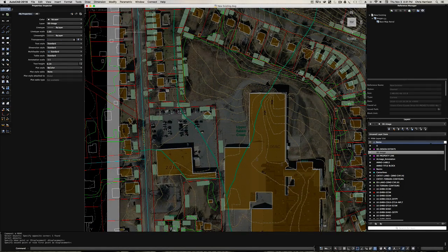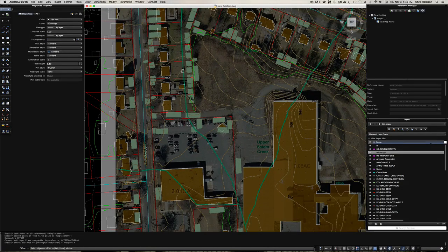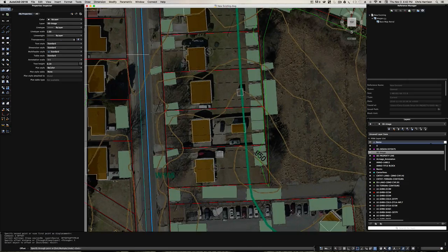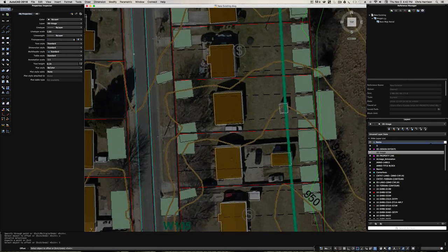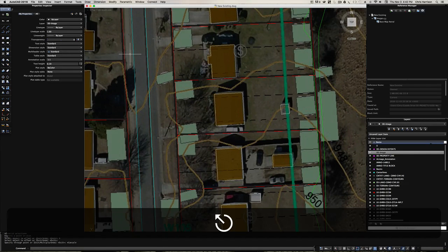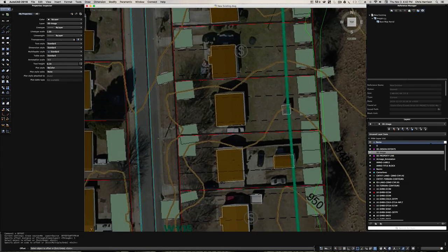I would use my, well, really just offset from your center line. So we can offset and through. And you would just offset these things through. It looks like the edge of pavement there. I know that now from that should be 1 foot from edge of pavement. Oops, offset 1, enter, and then to the side that you want.